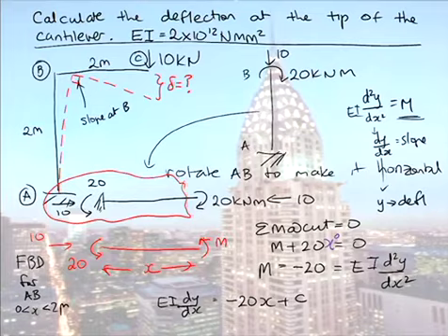Now to do that, you take moments at the cut. So I've drawn my M value in there, that's what I'm after. To be precise, I should have a shear in there as well for equilibrium. These two forces, 20 and 10 here, are the reaction forces down here that I've calculated at the support. So taking moments at the cut, I have M, I have plus 20. There is no vertical force in this case, so that's all I get for my moment.